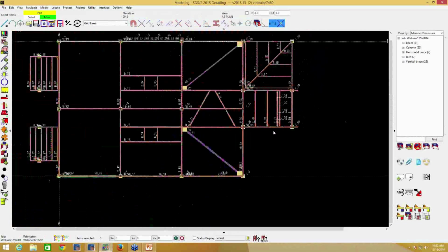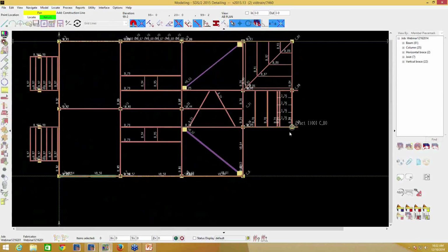Now with the picking of 2 points, with point locators, if you tried using perpendicular or angle, this will create an infinite construction line even if you use your finite construction line add tool. So if I pick my first point here and then say I want to go perpendicular to this line, it's just going to throw in your infinite construction line, picking either perpendicular or angle there.